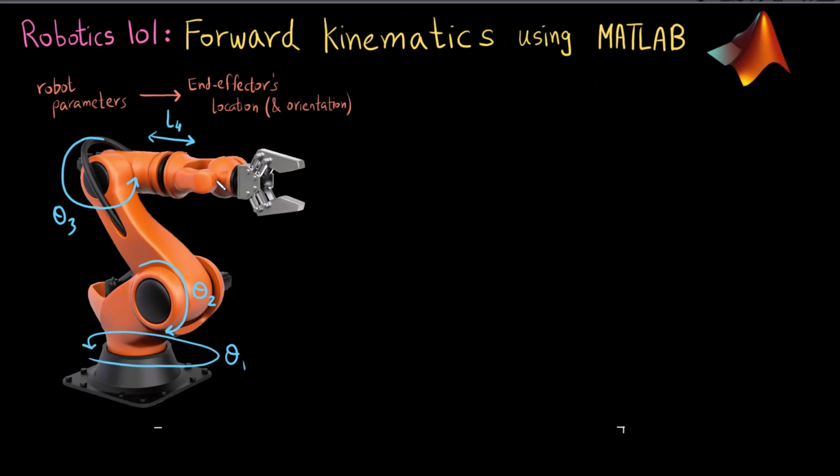And then right here, you can see that it can first rotate about this direction, which is a revolute joint. I can call this theta 5. And then right here, it can revolve around this direction as well. I hope that makes sense. So it can first rotate about this direction and then it can revolve about this direction. So theta 6. So now we can see that the robot parameters of interest are theta 1, theta 2, theta 3, A4, theta 5, theta 6.